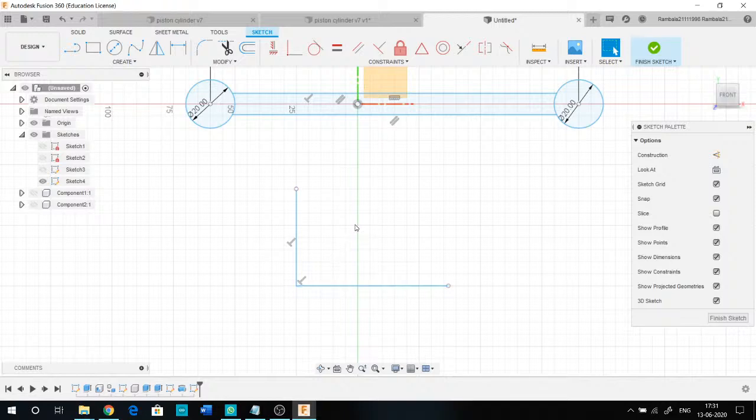If you want to change the angle, actually these two are right now perpendicular. This constraint is displayed, right? You could just right click on it and delete that constraint. If you want to change the dimension between these two, go to sketch dimensions. First click on this particular line, and next click on this line again. Now you will be able to see the angle between them.